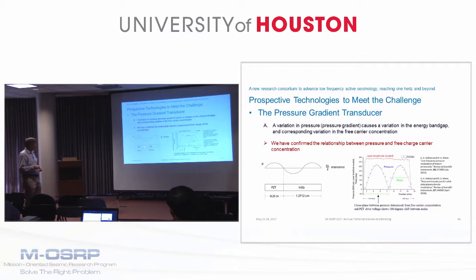And so we used that and measured at numerous points along the length of the InSb. And from the measurement of the carrier concentration, working back through the band gap and so forth, we inferred what the pressure in the material is. And that's plotted here with the blue dots.